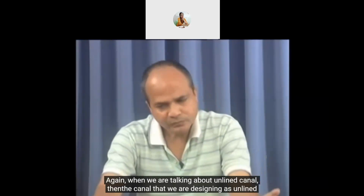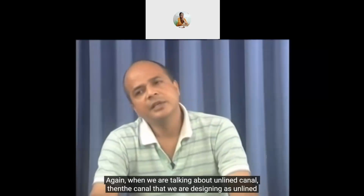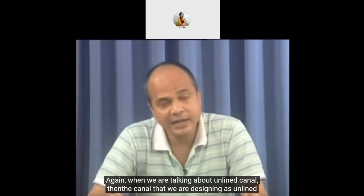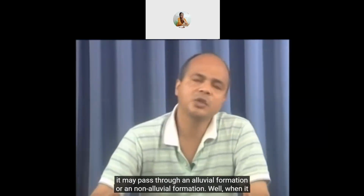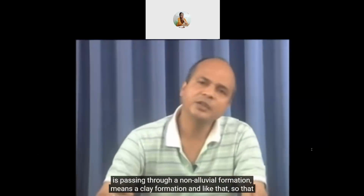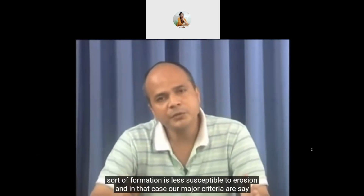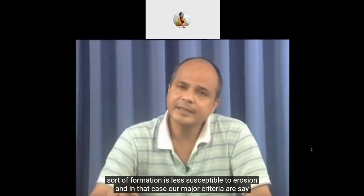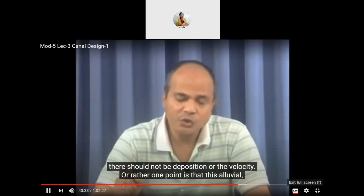Again, when we are talking about an unlined canal, the canal that we are designing as unlined may pass through an alluvial formation or a non-alluvial formation. When it is passing through a non-alluvial formation, meaning a clay formation and like that, that sort of formation is less susceptible to erosion. In that case, our major criterion is that there should not be deposition.